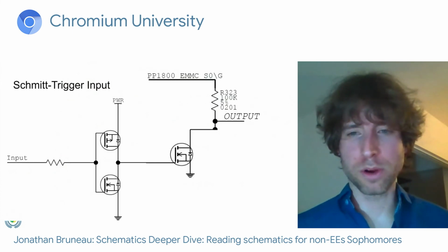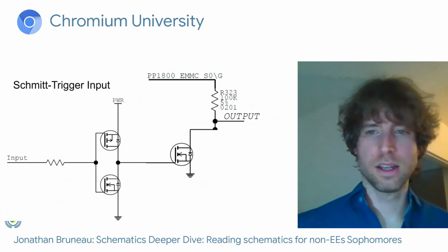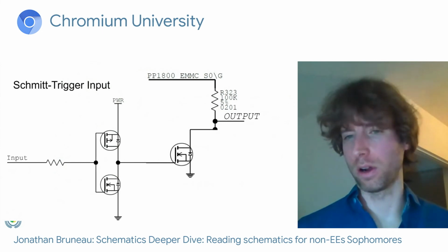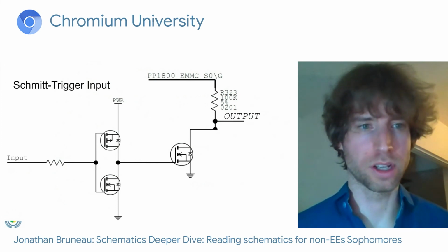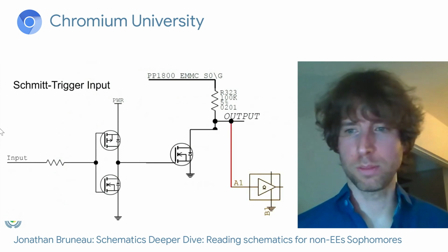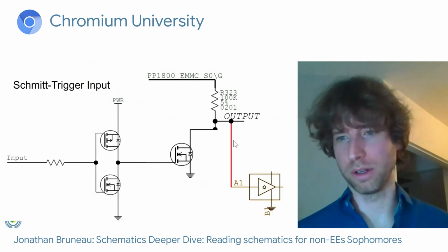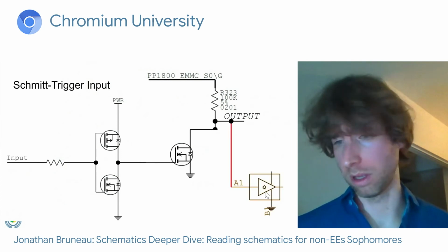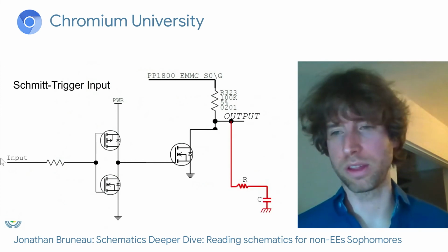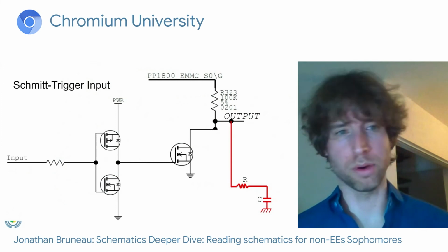Really, the Schmitt trigger makes sense when you look at what happens downstream from our logic circuit that we just talked about. So this is, again, the same circuit we had before. And suppose that I'm tying my output to another gate, and I just picked something, it doesn't matter. The point is that we end up with another RC input.